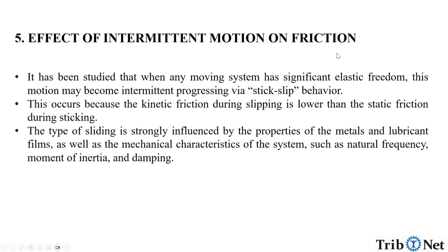Effect of intermittent motion on friction. It has been studied that when any moving system has significant elastic freedom, this motion may become intermittent, progressing via stick-slip behavior. This occurs because the kinetic friction during slipping is lower than the static friction during sticking. The type of sliding is strongly influenced by the properties of the metals and lubricant films, as well as the mechanical characteristics of the system, such as natural frequency, moment of inertia, and damping.